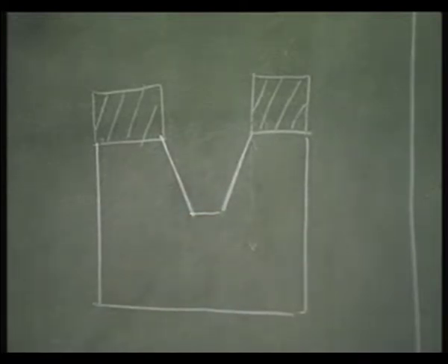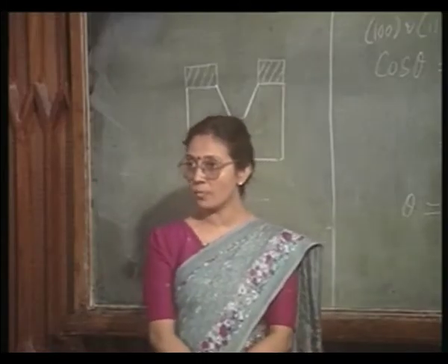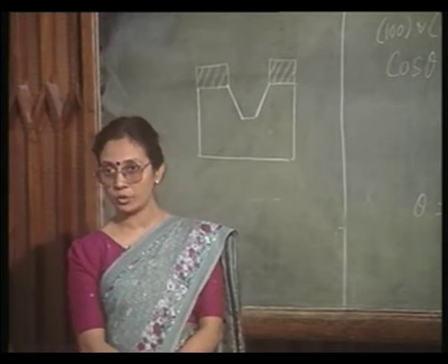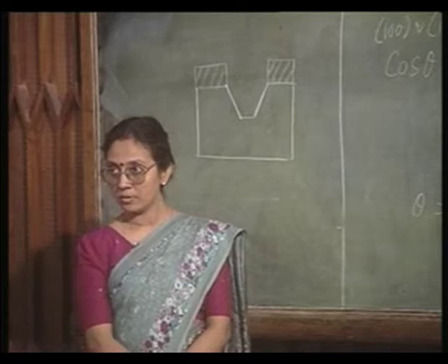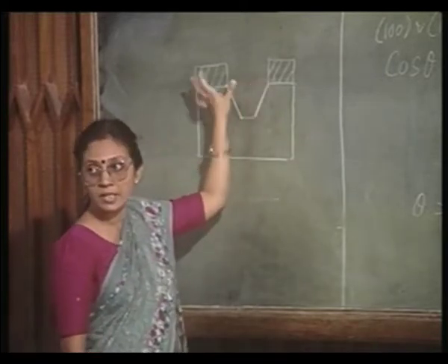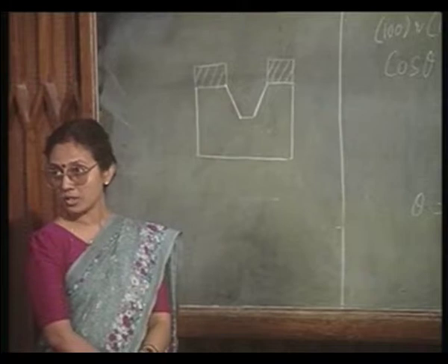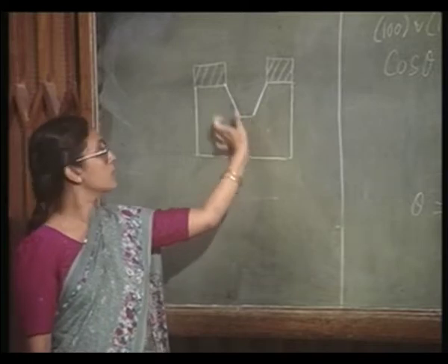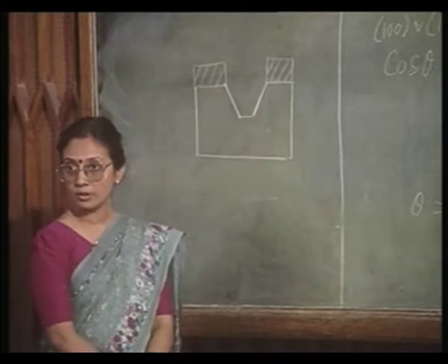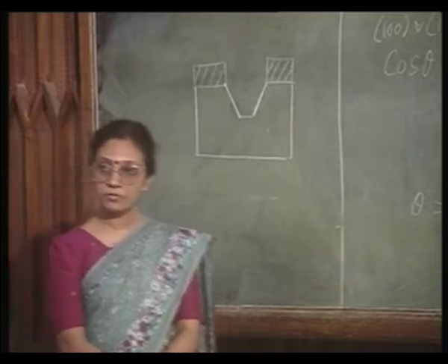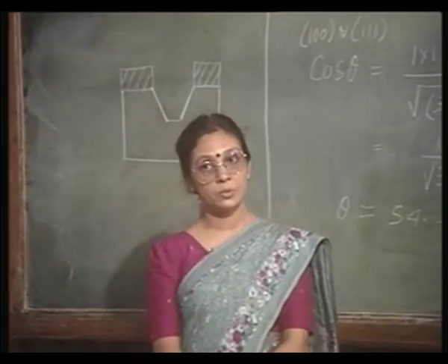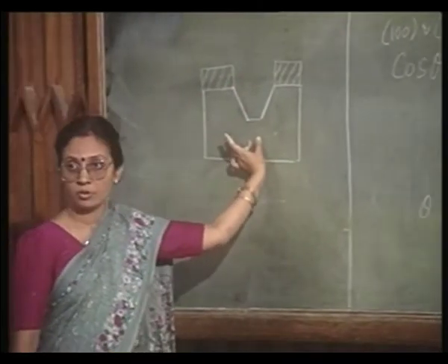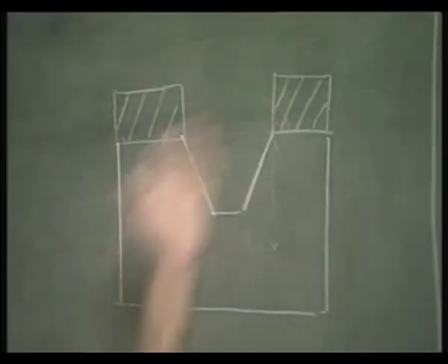So, what have you achieved? You have achieved a MOSFET with a very small channel without actually having to have very crucial photolithography. By deciding the time of etching and by keeping this window dimension, you can actually realize a channel length which is going to be much smaller than your original window opening. So, it is used in VMOS. It can also be used in isolation between two devices. If you can etch it down, you can have one device here and the other device here.